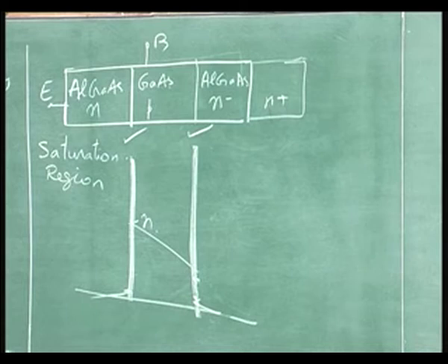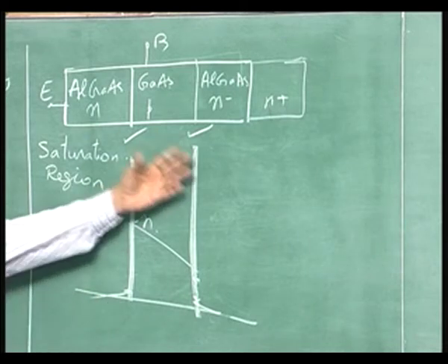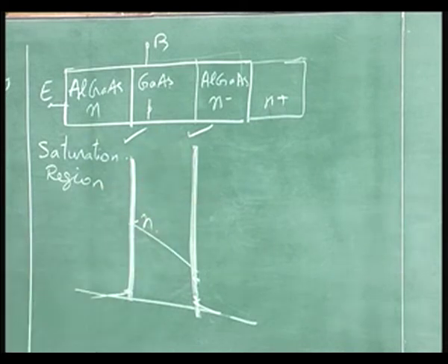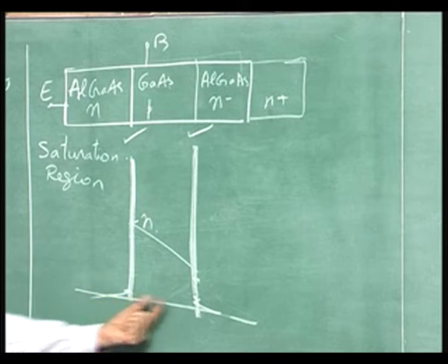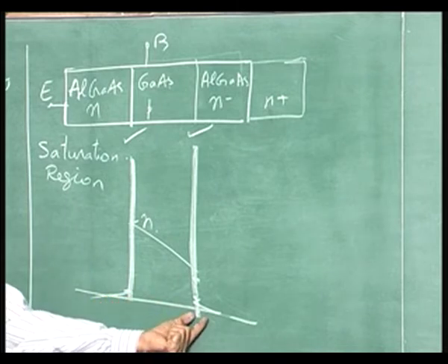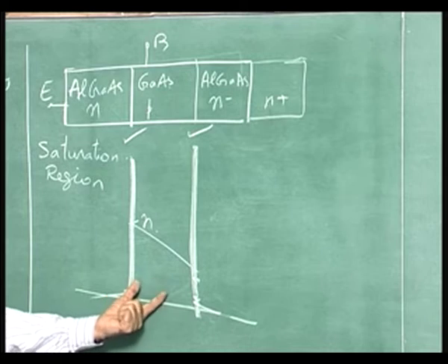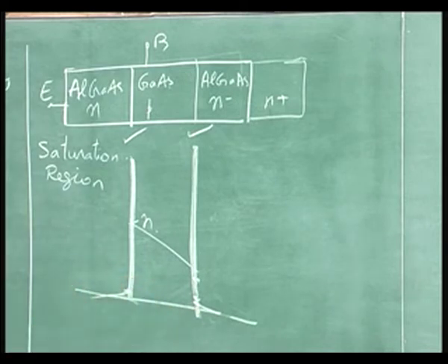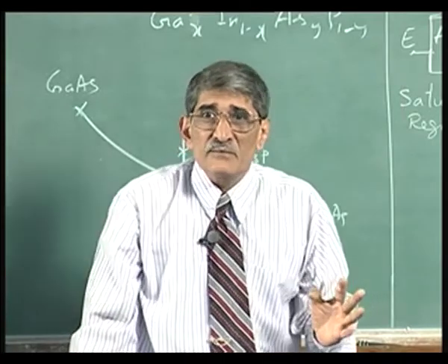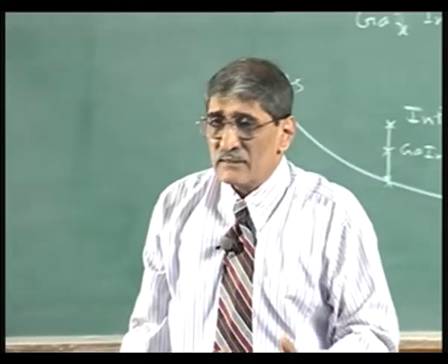So, that is what we mean by saying that the transistor will go to saturation, still you will not have the stored charge effect. For switching transistors, the double heterojunction will be ideal. You do not have to use lifetime control techniques, etc. All that you have to worry about will be the charge in that region. No charge here, stored charge here, no stored charge here, because it is wide bandgap material. Stored charge here can be minimized by shrinking the base width. So, you are in business for high speed circuits. That is one of the merits of double heterojunction transistors.